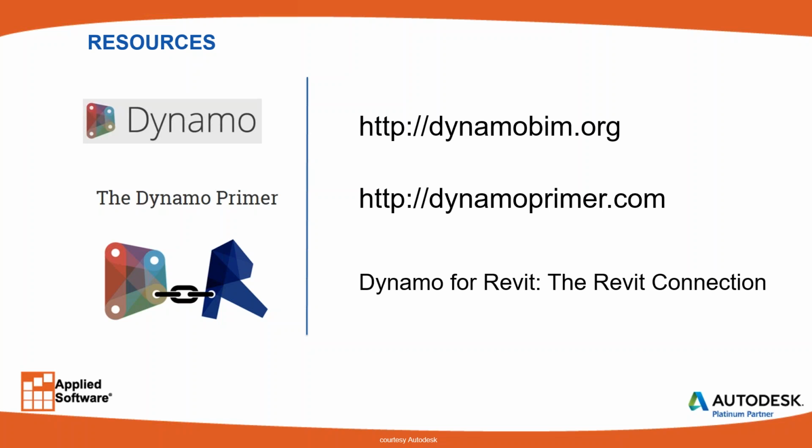You'd have to create basically an add-in for Revit that shows up in the menu and does a specific thing for you in your business. So if you have a single complex issue to solve, Dynamo is the right tool. If the issue repeats on every project or on most projects and most future releases of Revit, then you probably need to talk to us about the best way to do that using the programming languages of Revit, not just Dynamo.